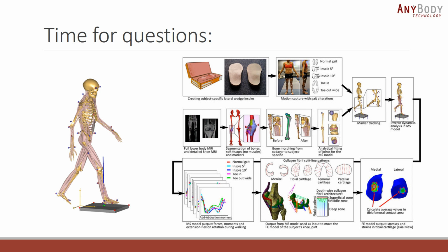So what we did was that on the femur, we defined one point, and then around that point, we summed up all the contributions from the muscles, the hip joint reaction force, and gravity and inertia. The things we didn't include in that force were the reaction force between patella and femur, and the ligaments, and between femur and tibia, because those we wanted to model in the finite element model.